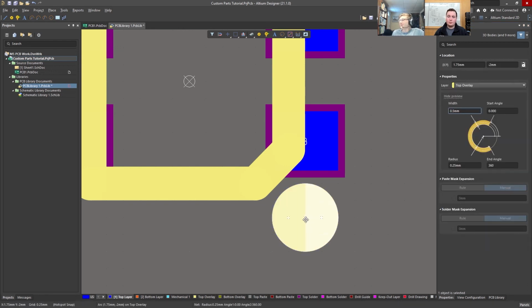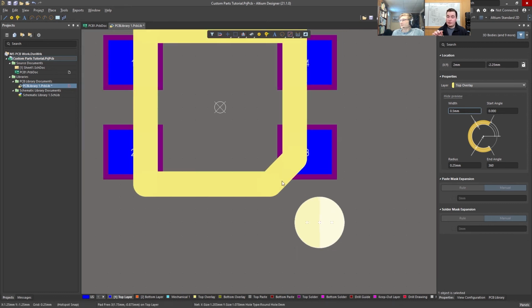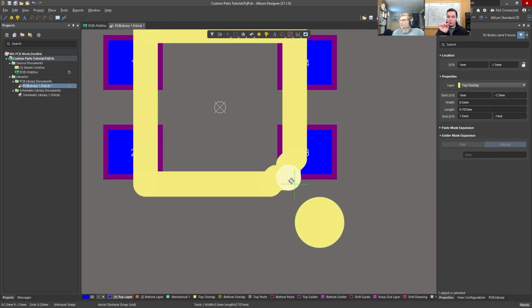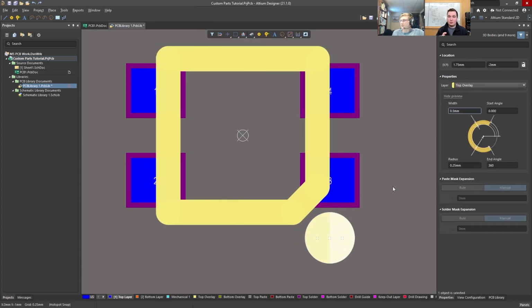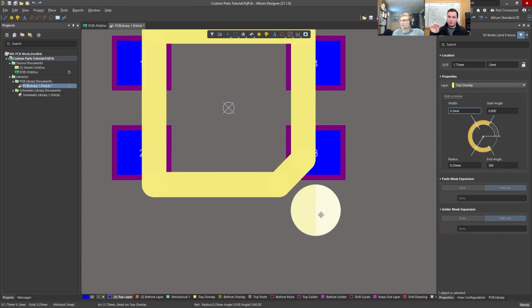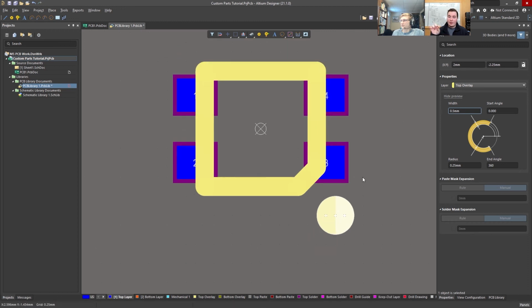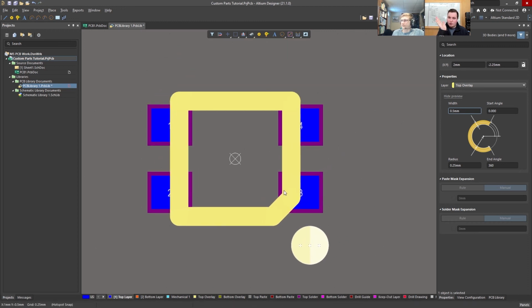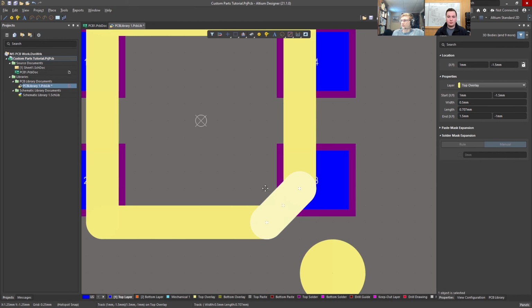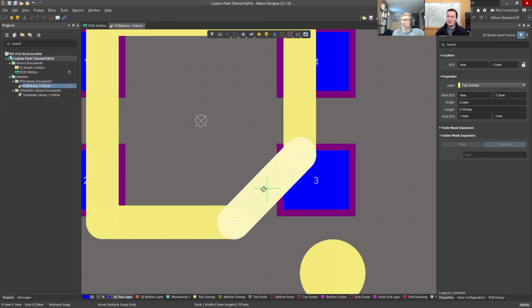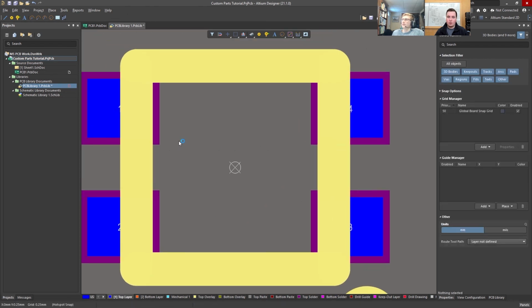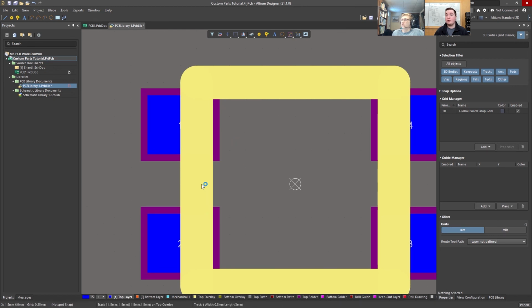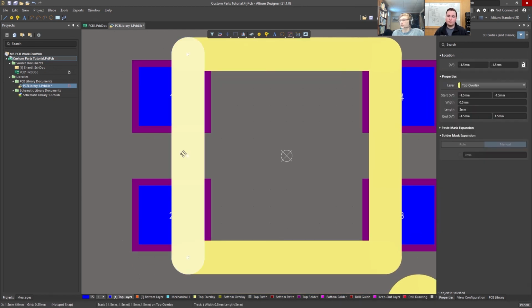My mistake. And as a small warning for anyone who has enough room to do the notch that Chris showed, make sure that your notch will fit your minimum printable differences. So we might even want to go a little more in for the chamfered corner, just a touch. You might do it like that or something. Yeah, like that. But like I said, we can't really do that so well because we can't have writing going over our pads. That's not going to work. They won't produce that. So how do we fix that?